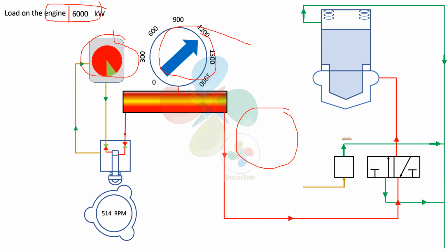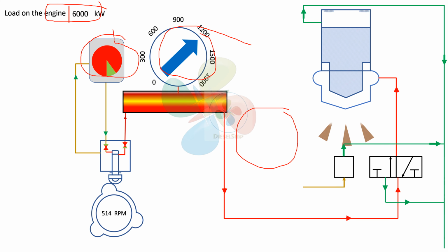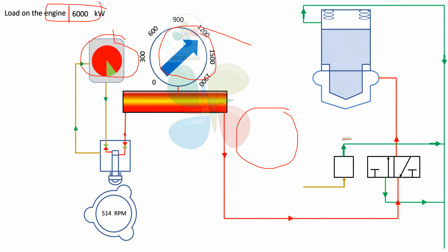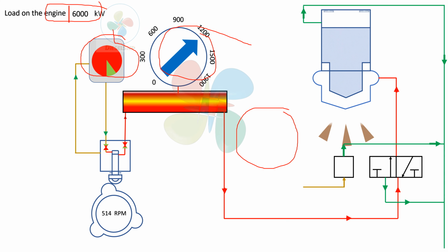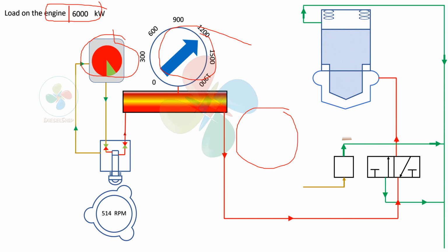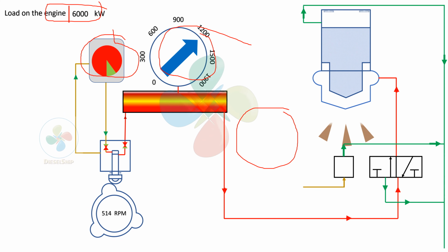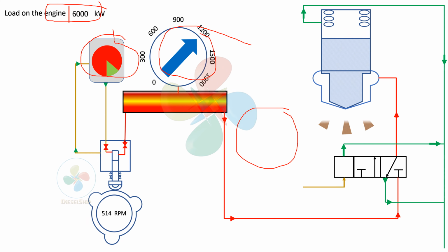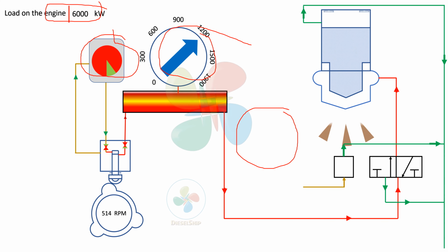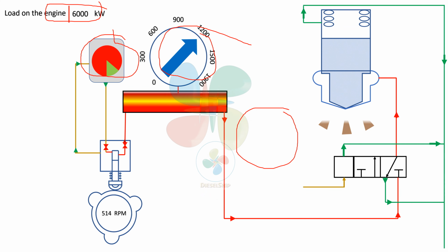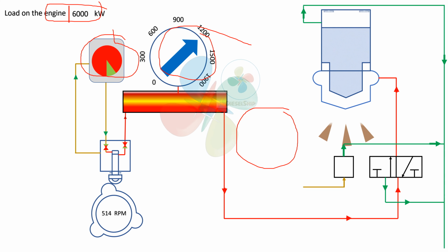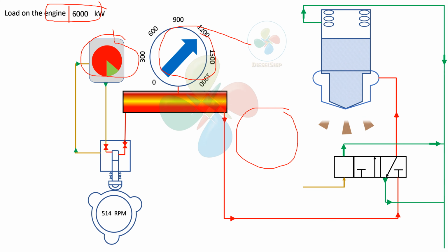See, what happens in a conventional engine is that we have a helical groove and a plunger turning and all this stuff, right? Mechanically, we are increasing the volume of the fuel admitted into the injection components. But here, it is really good. You know why electronic engines are so successful? Because the timing, metering, injection, everything is so precise and flexible without relying on any mechanical action, right? If there has to be a mechanical action, there have to be so many mechanical linkages involved, causing lag. So there are a lot of other factors; it is not so easy.